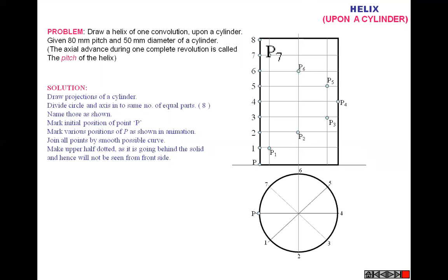Now we can trace the point here. Similarly, draw a vertical line from each point of the top view, which intersects the horizontal line at this point: from 1 up to the intersection here. Draw a vertical line from 2 which intersects the horizontal 2.